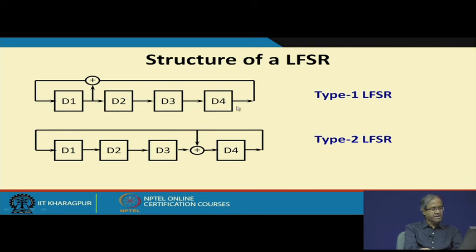You see, this LFSR does not have any external input. Once you load it with an initial value and apply the clock, it will keep running in an autonomous fashion, generating patterns continuously.